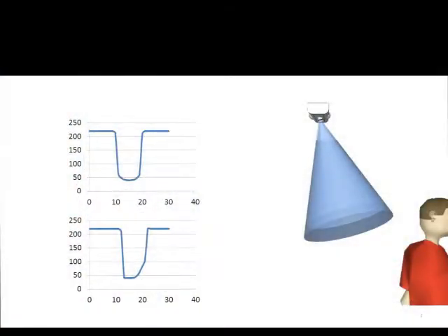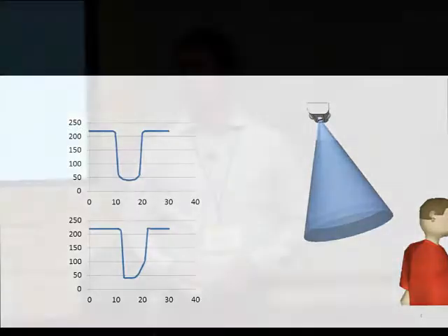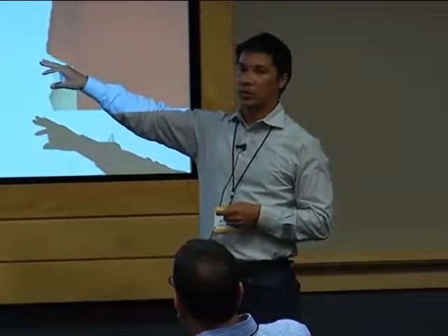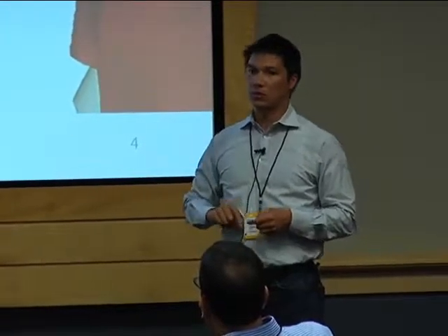The reason for that is to figure out who's actually walking through the door. You can imagine a conical sensing region of this ultrasonic rangefinder. When the person walks under the door, the distance measured at first points to the floor, so about 7 feet, plus or minus. When the person walks through, you get a shorter distance, the distance from the door jamb to the top of the person's head. That can tell you roughly the height of the person, the difference between those two readings. And you can identify the position where the person walked directly under the door, hopefully, because that's the shortest distance that you measured. Now that tells you who walked in the door, more or less, differentiating between the people in the household, at a household scale, where you have 4 to 5 people living there. It doesn't tell you which direction the person went in, so you don't know which room they went into.